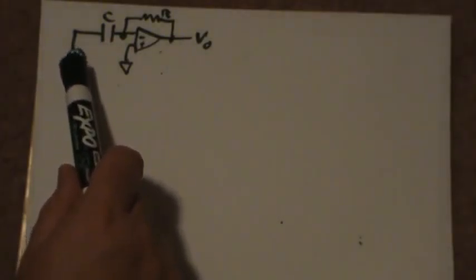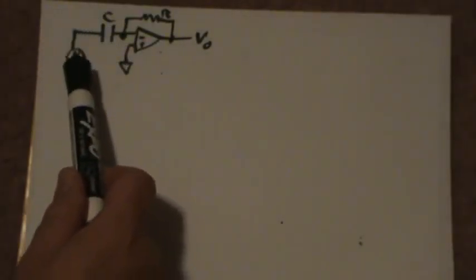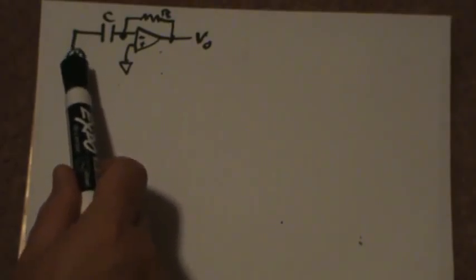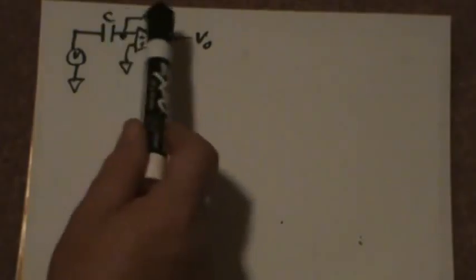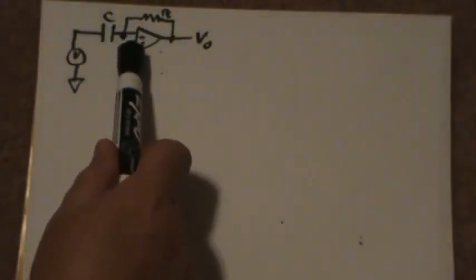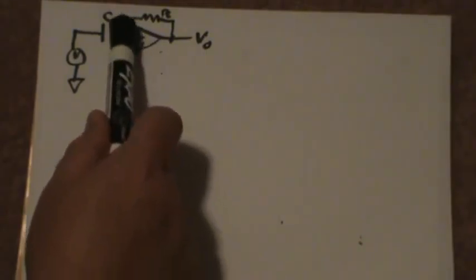This voltage source, let's assume that it's got a time varying signal. If it's not, this is a very trivial circuit, because if it's a DC circuit, it's going to hit this capacitor. DC values cannot pass a capacitor, so boom, we're done. The signal becomes zero, and this becomes kind of a ground. Nothing is driving this at all, and the signal is all over with.